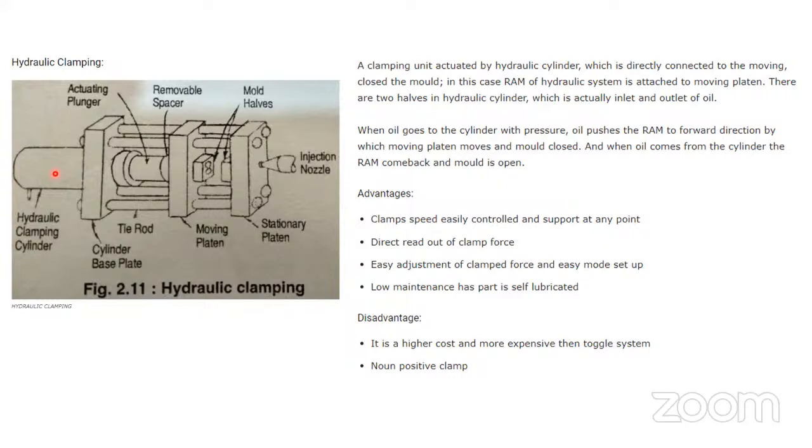And therefore, you are not providing a constant pressure here. You want 120, but you don't get 120. You want 120 continuous till the injection finishes, till the mold opens. But no, here from the injection, closing, to the mold opening, the pressure varies: 119, 118, 120.